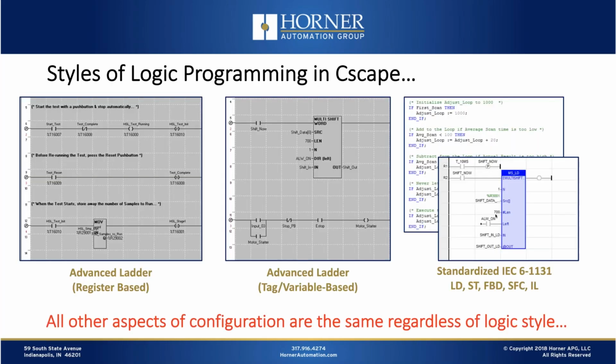All right, let's start by looking side by side at the different styles of logic programming in Cscape. First of all, if you are configuring screens or configuring your hardware, setting up your communications, all of those ancillary functions that are key to the application, those are done the same way regardless of what logic style you choose in Cscape. But you do have some choices in terms of the logic options, starting with advanced ladder, which is the register-based version. That is currently still, it was the original approach and still the most popular.